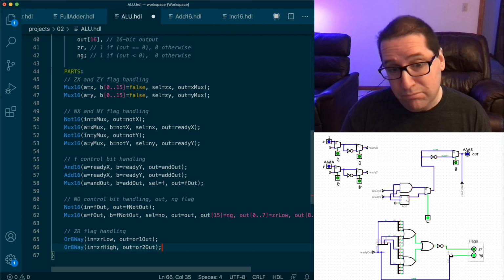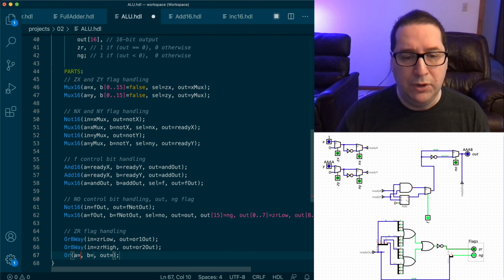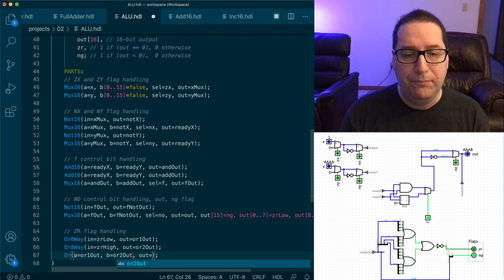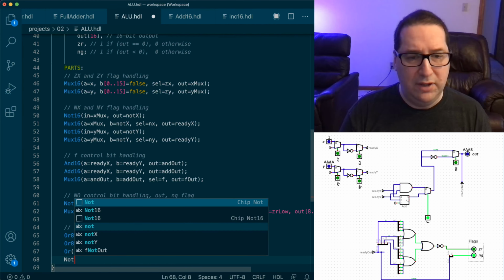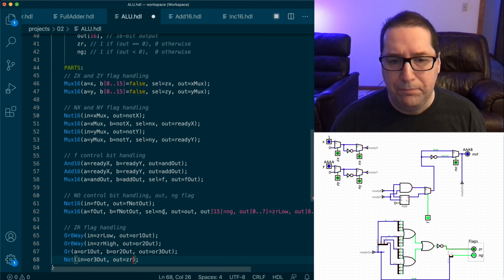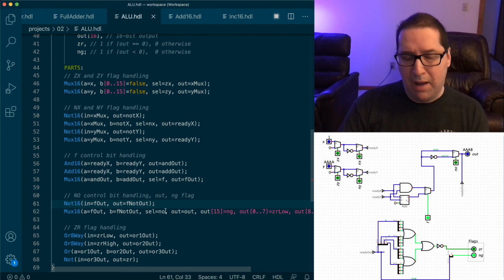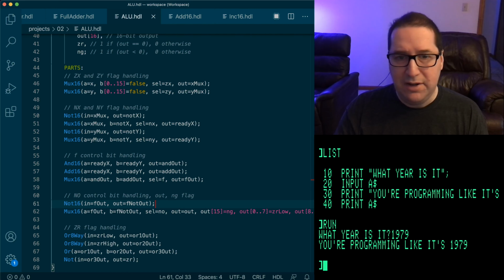If it turns out I do, well, I'm glad I just gave a lecture about making mistakes. Okay, then we just need a normal OR gate. We need a 2-bit OR gate. And call that OR3 out because I'm boring. And then lastly, we need a plain old 1-bit NOT gate, which is going to take OR3 out and wire that up to ZR. My belief is I may have made a mistake, I may have typos, but this feels pretty close to me. Let's find out how I did.